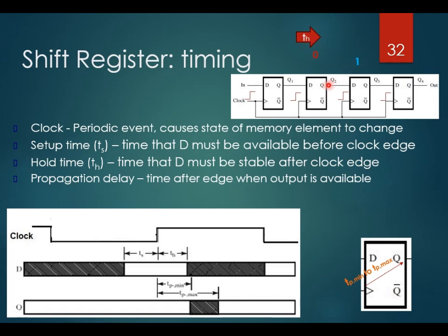So it is safe for 1. The 1 is still staying at Q2 when 0 is still halfway propagating to Q2. By the time it reaches Q2, because it is longer than the hold time, it is already past the hold time window. So the signal 1 has stayed long enough at Q2 and doesn't violate the hold time for this flip-flop.